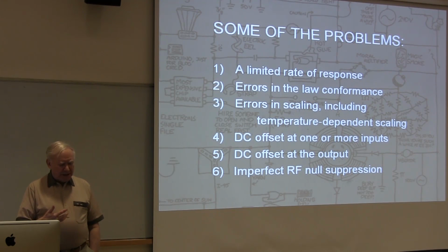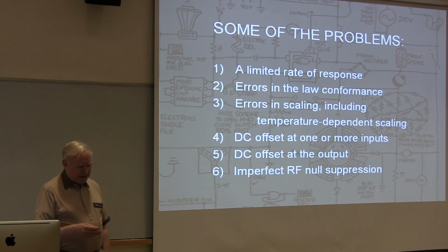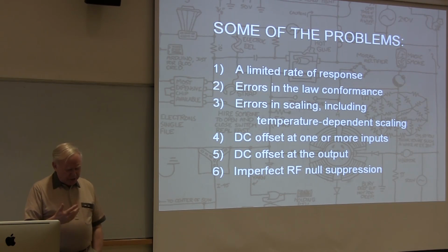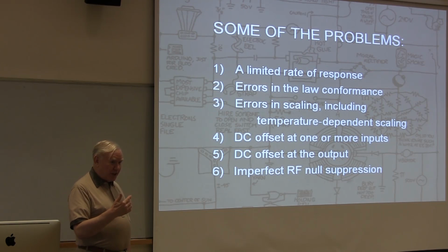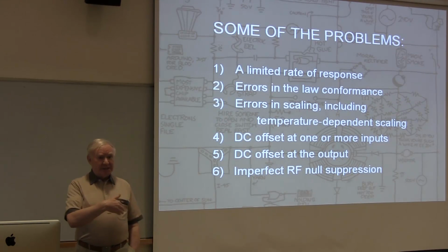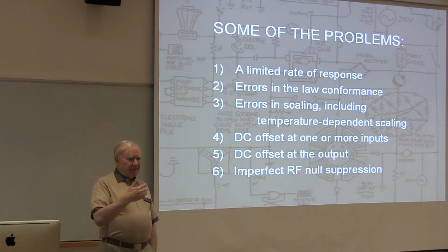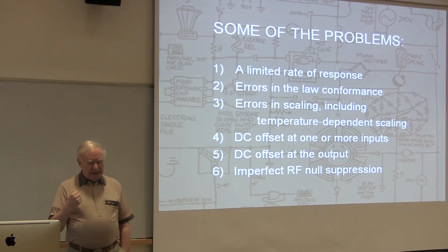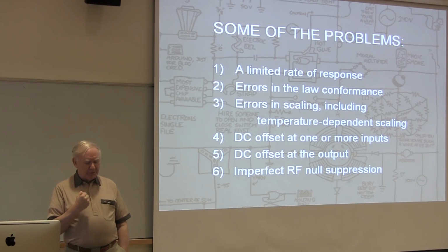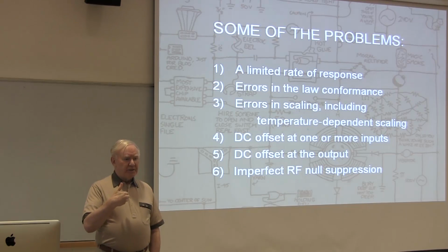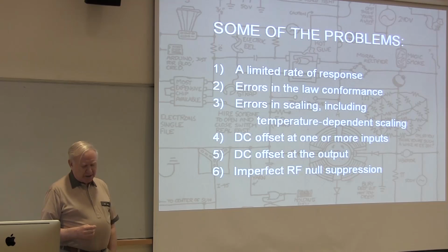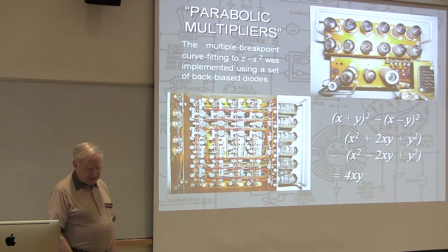Okay, now some of the problems with any mechanical system, of course, are all these. And these are problems shared by some circuits as well, apart from mechanical stuff. So they have to be dealt with, and nowadays we resort to laser trimming. I'm not ashamed to say it. It doesn't cost all that much. Someone was asking today, how much does it cost? Anything from 1/10 of a penny to about 2 cents to do a complicated laser trim. And it's really a very powerful means of improving the performance of a circuit without having to deal with some complicated digital engine that does it all for you, which I know is of interest to you guys, but we're lucky to have laser trimming, and we're going to stay with it.